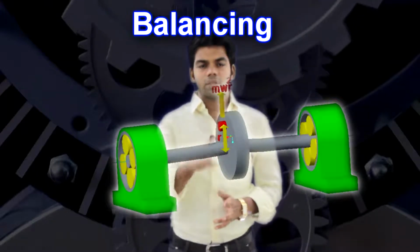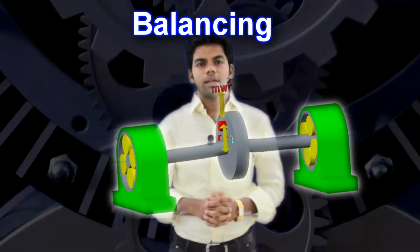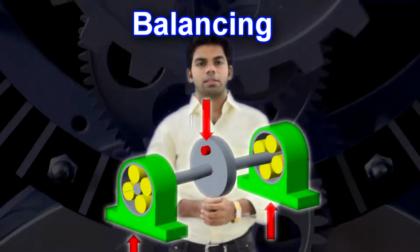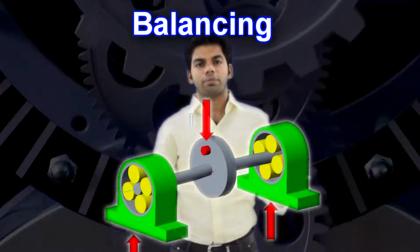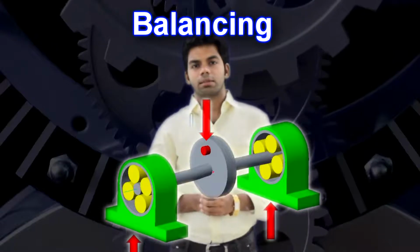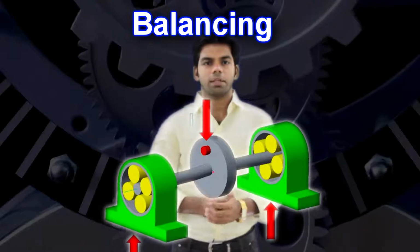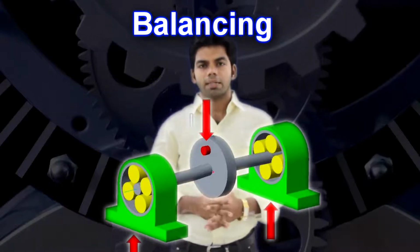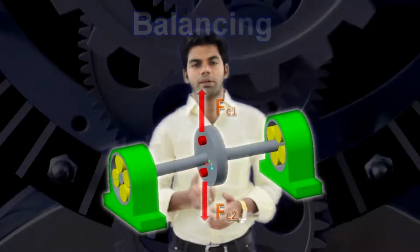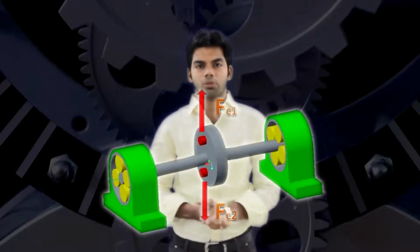Because of this centrifugal force, an acceleration is produced in the outward direction, and therefore an inertia force is produced in the inward direction, as you can see here. Because of this inertia force, it will affect this bearing. So it is very important to balance this rotor, which is unbalanced because of this unwanted disturbing element. How can we balance it? We can put another mass, so that an equal and opposite force is produced on the other side of the rotor, to be very simple.